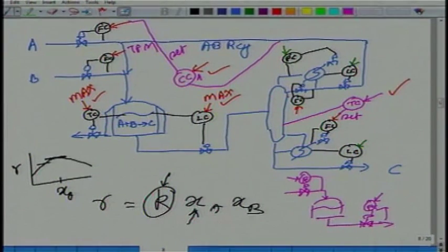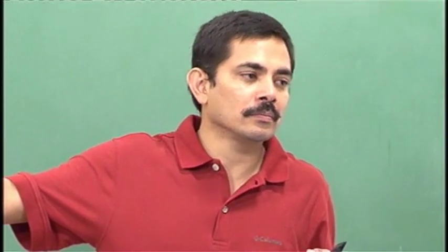Whatever you are putting in must get consumed in the reactor. If it is not getting digested or reacted away in the reactor, it can't go down the bottoms. It's going to build up in the recycle loop. So the component inventory is behaving like a level. The mismatch can be very small. Maybe it will take months for the inventory to build up.